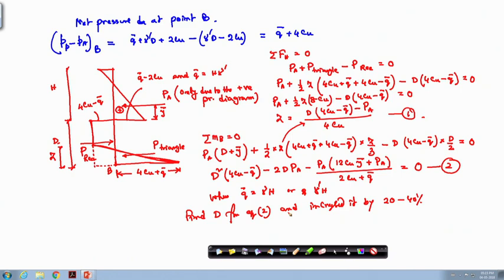Okay. So, the solution process is the same as the problem I have solved for the granular soil case, because here you have to use these two expressions, and Pa you will get from this triangle. But remember that there may be some C-phi soil also in this top portion. So, depending upon your soil you will get an earth pressure distribution diagram. So, you take the positive part of that diagram only and get the Pa value and calculate the y bar, that I have also shown how to calculate, and then you will get this z expression, put those values.